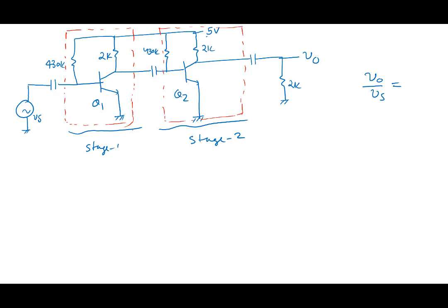Each one of these blocks is, we said, basically this. Remember, Rn, voltage source, AV0 times V in, whatever is this V in, this V in plus minus, and this R0. That's what this particular block is.